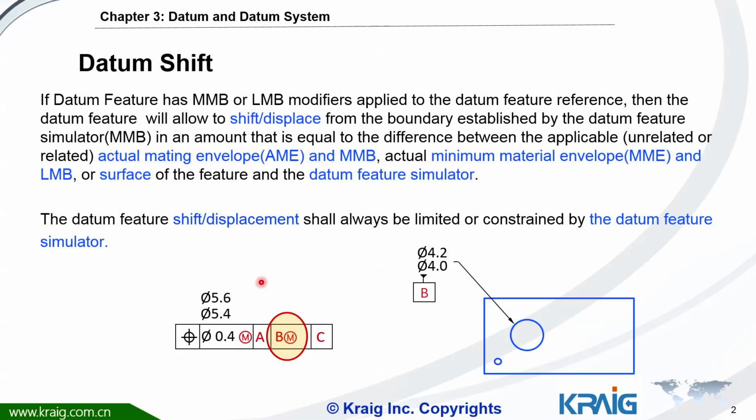Basically, it's talking about if the datum is a feature of size, and once the datum is not at maximum material boundary. For example, here maximum material boundary is 4.0. This is the worst case. And once it's not worst, for example, it becomes 4.1 or 4.2, then this part is allowed to shift, to displace, to move on the datum B. So if you look at the whole sentence, it's talking about this.